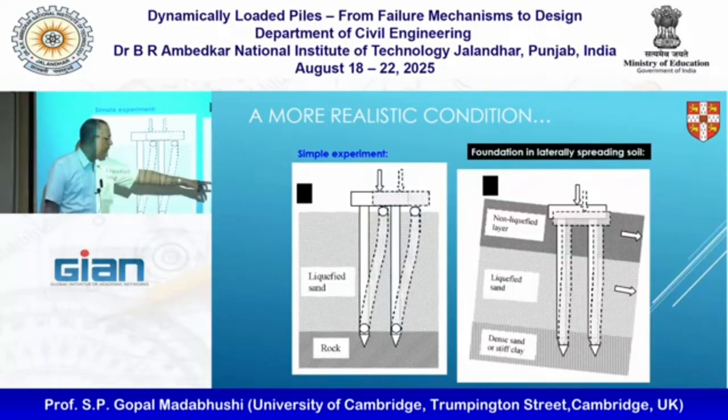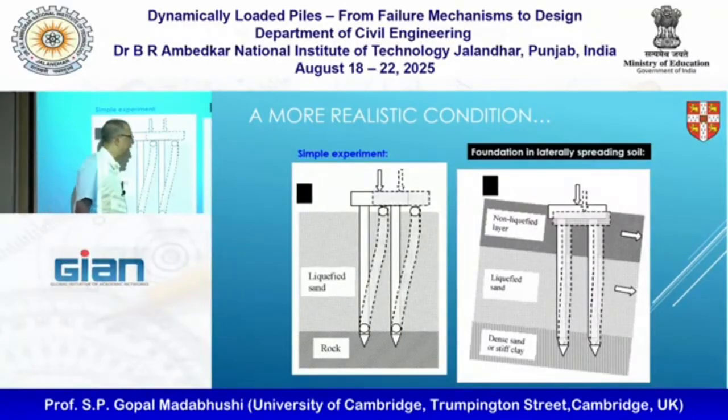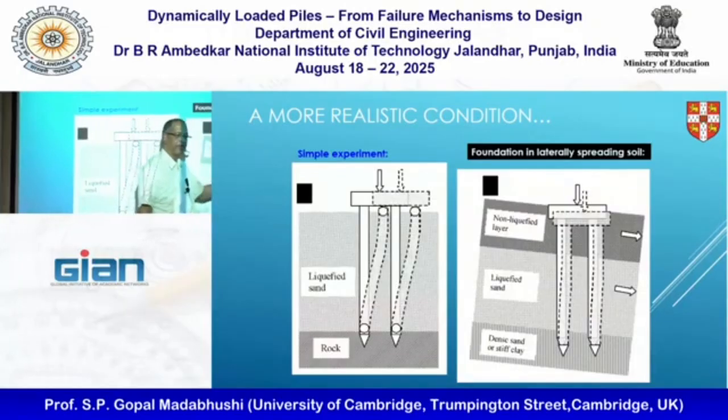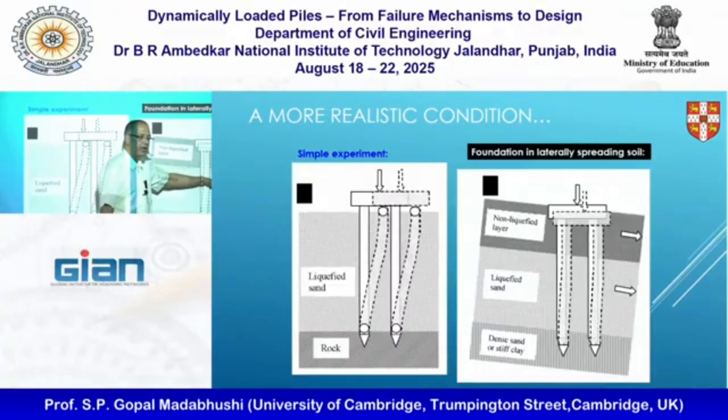So these kinds of piles very rarely will buckle, because the buckling load will be a lot higher, and it's easy for the pile to settle. That doesn't mean the pile won't have bending. The pile has settled, but it is also trying to bend a bit. So you're still in the bending regime I showed you in the morning.